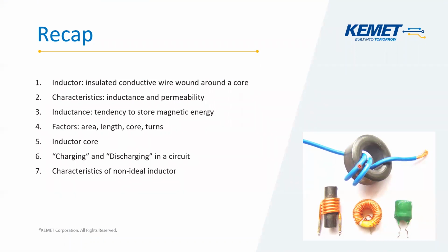I should take the opportunity to mention that one of the most common modes of failure when it comes to inductors is that you lose insulation between the different turns. Very commonly, too much current is passed through the coil, and the coil heats up so much that it melts that insulation, and then you get a short between two or more turns. If that happens, you no longer have an inductor. It just doesn't function as an inductor anymore.